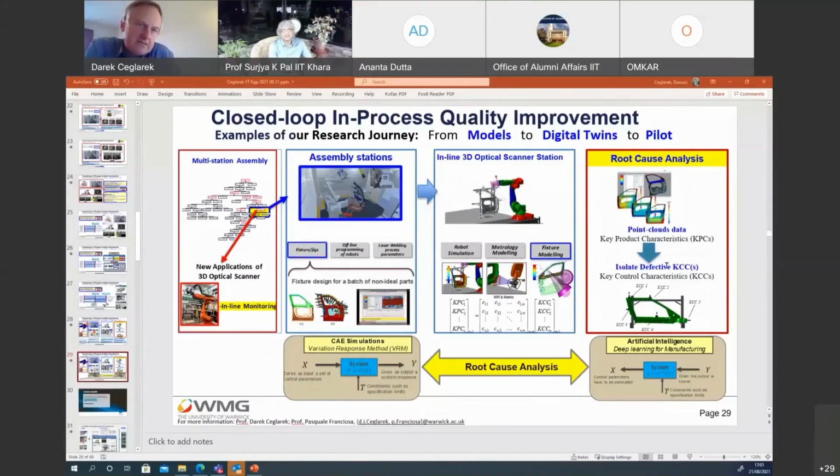We link, for example, component part variation to the fixturing, and we design the fixturing process based on this part variation, a batch of parts with variation. Based on that, we try to minimize, for example, gaps in the case of welding, the gap between the components. From the simulator, we know what gaps we can get, and based on this gap we try to see how to match it with the process to have a robust process under uncertainty. So the logic is how to make a good assembly with bad parts. I'm exaggerating a little bit, so maybe not exactly this way, but how to make a good assembly with errors embedded in the components and in the process.